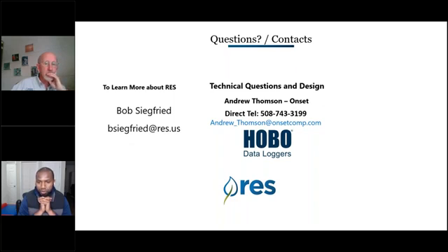It's saying that USGS has had real-time stream gauge data for decades. Why did it take so long for this technology to show up in mitigation? The missing link really was that wireless transmission. Mamadou mentioned it: a sub-gigahertz radio signal that pushed the data from the sensor out to the base station that had the cellular connection.